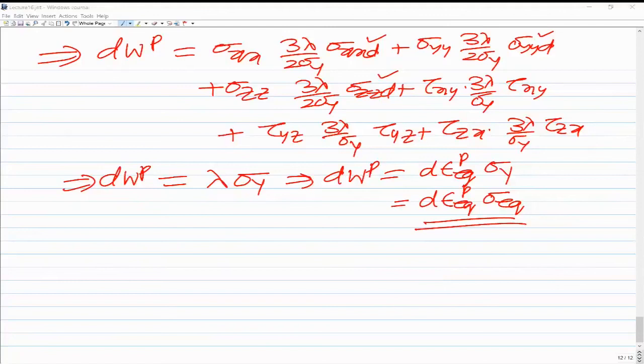The integration limits are different, but when you look at the expressions, the shape functions also are going to be different for the global coordinate system. But when you take the derivatives and integrate after multiplication, that result will be the same. That is the only confusion, sir, because in the A matrix, all are represented by x1 and y coordinates.